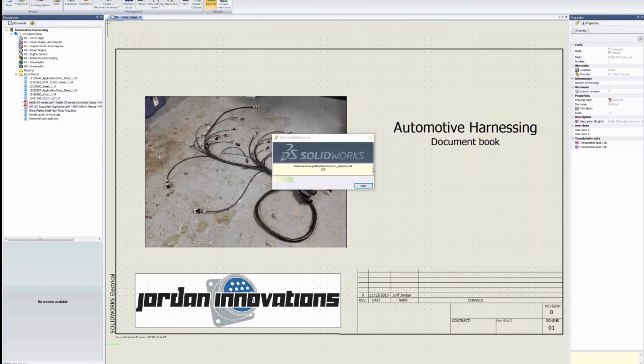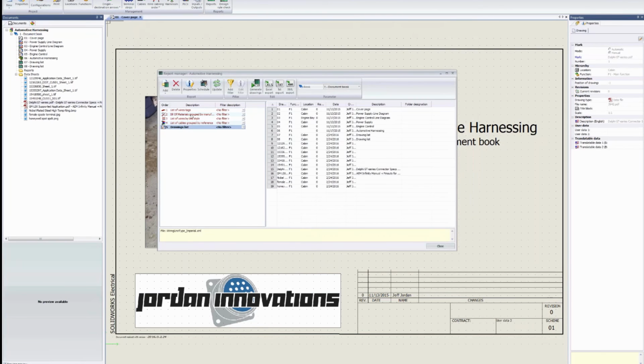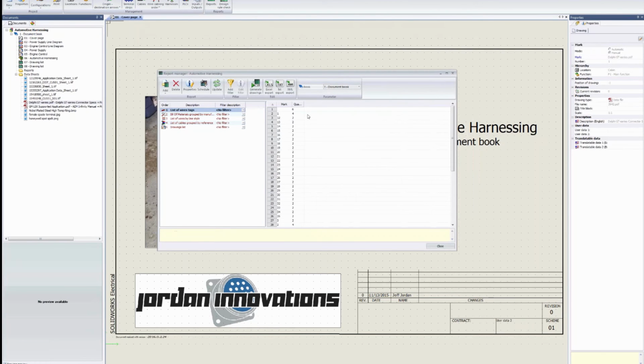So I'm in here in my reports. It's telling me about what's in here in drawing list. Great. What I'm most concerned with is these wire tags. So we all want to tag our wires, right? We're using harnesses, so wire numbering is kind of all we got. Here I'm using individual wire marks. So these are our wire marks from the automatic wire numbering that took place.